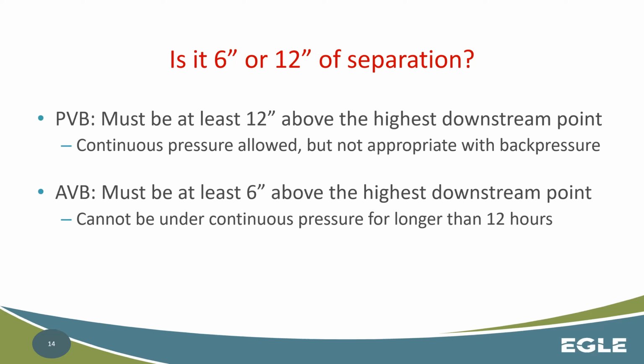If you install a Watts versus another brand, like Zurn or something with a Z, they all will say different things. One manufacturer says 12 inches, the other says 6 inches. So we're trying to say pressure vacuum breakers at least 12, atmospheric 6, but this is an ongoing debate. This might also become 12 at some point for those.